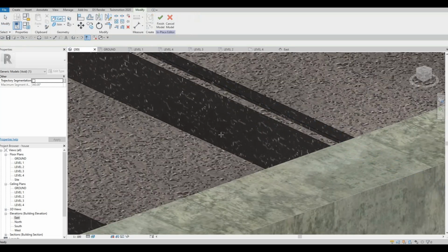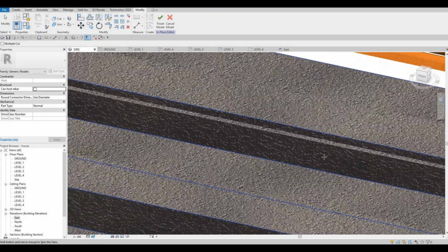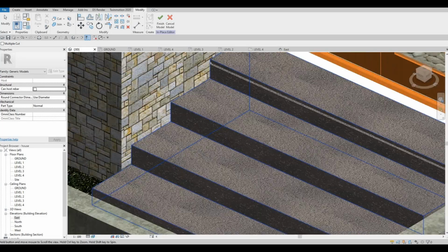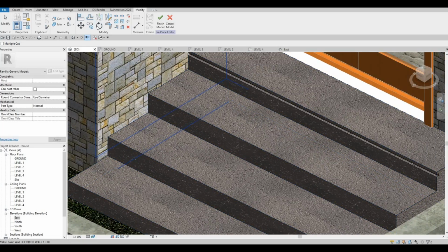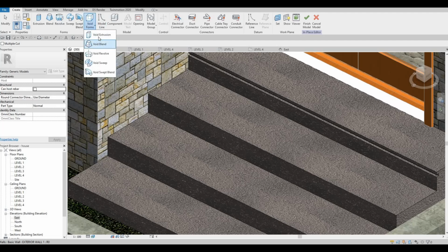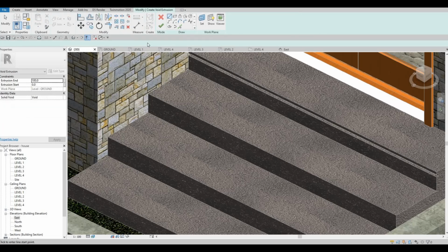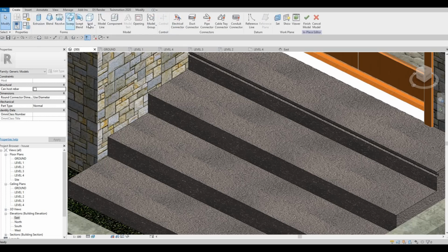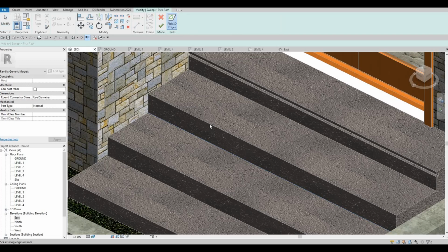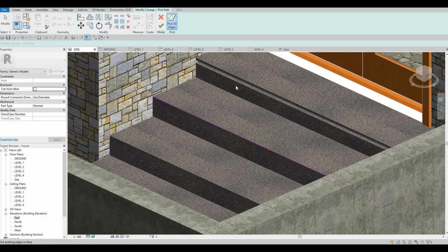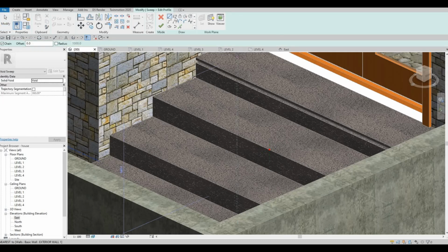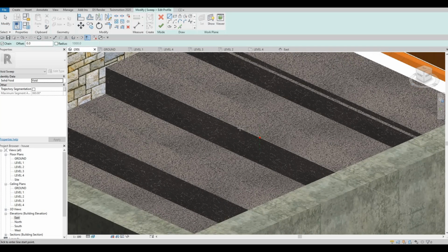And then you could do cut geometry so that you can see it instantly, and we need to do it 3 more times. So click here, void extrusion or void sweep, select this one, click finish, edit profile, and then 20.